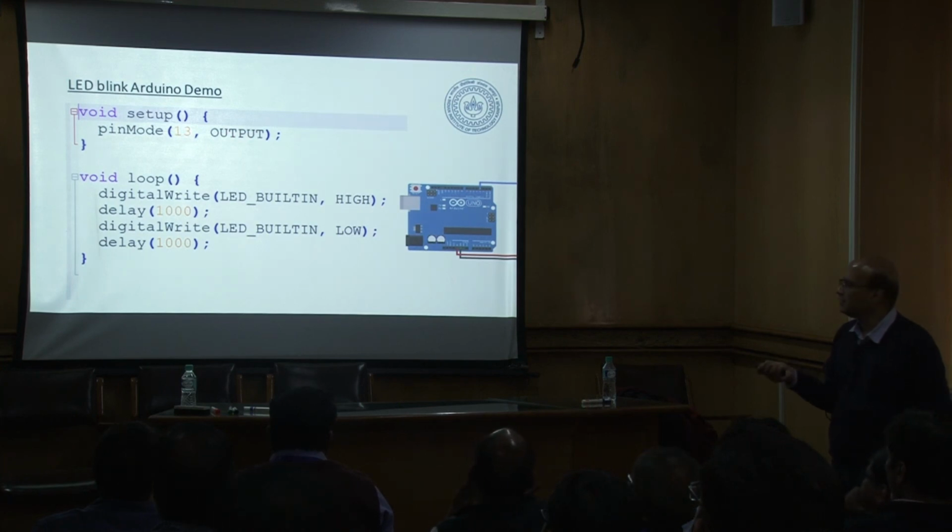Then we say digitalWrite, LED built-in, which is this one, and we say high. Then we give a delay of something. Then we give LED. LED built-in is again an internal function.